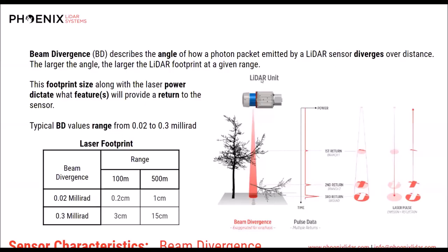Yeah, well, to be honest, forestry application of LiDAR really started from the fixed wing plane approach. So that's certainly a possibility. For our sensor portfolio, I'd highly recommend either the VUX LR or the VUX 240. Both, given the speed that traditional planes fly, will give you decent coverage. You may not get into the hundreds of points per square meter type of range, although with the VUX 240 that is very possible. But obviously that is dictated by flying height and speed.